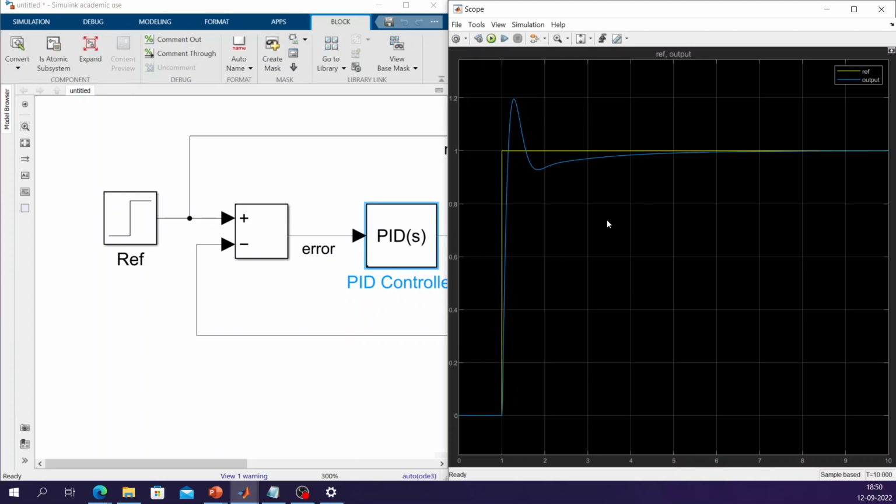Sometimes a hands-on quick viewpoint is that you keep increasing the proportional controller gain, then change the derivative gain so that you respond smoother, and change the integral gain so that you can quickly reach the steady state value. So that is what I have intuitively demonstrated here in the PID tuning section by hand.